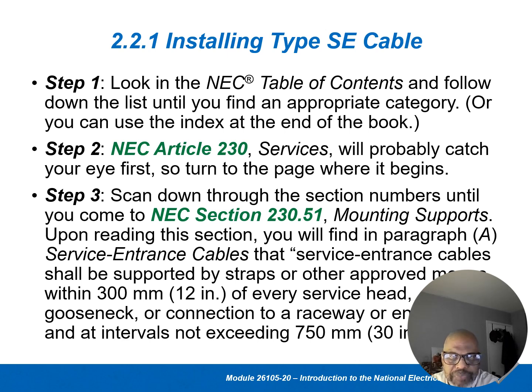Upon reading this section, you will find in the paragraph on service entrance cable that the service entrance cable shall be supported by straps or other approved materials within 300 millimeters, which is 12 inches, of every service head.